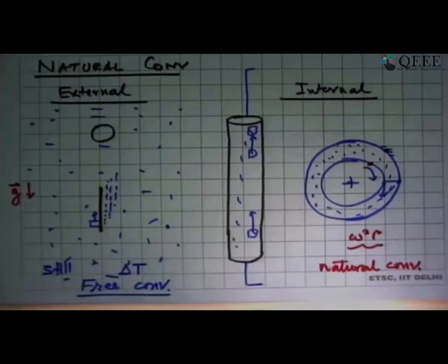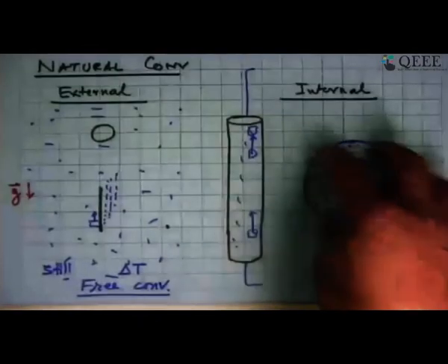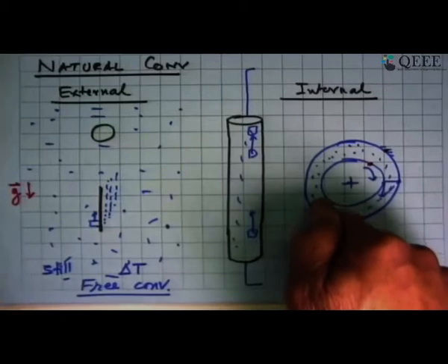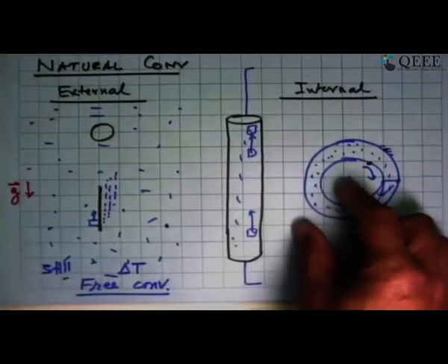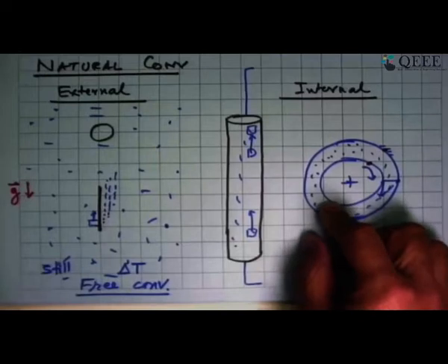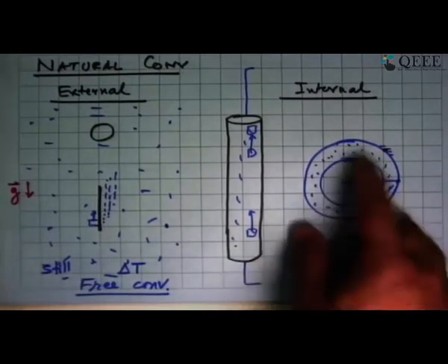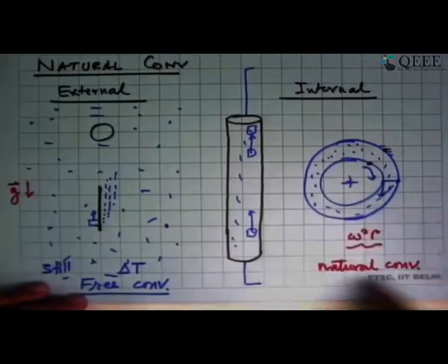It took a long time for people to realize why electric motors were burning up so fast, for they thought that in this gap in the motor, we will put a fan and blow air through this gap. And they calculated that this is an internal flow, something like an annular tube, and with forced convection equations, we will calculate the heat transfer coefficient, and that we can predict what the temperature should be. When they did the design on that basis, it did not solve the problem. Rotors continued to burn out unless they looked at this part of the issue.